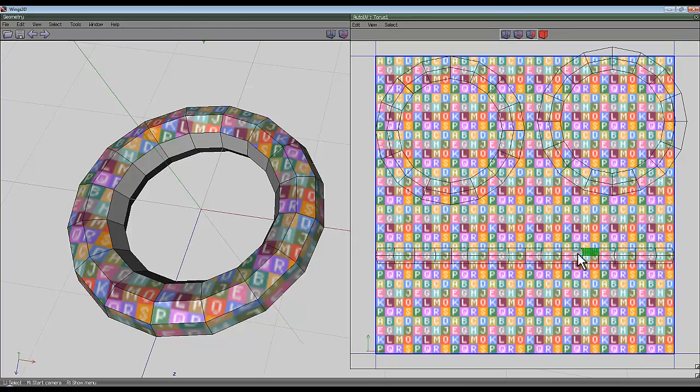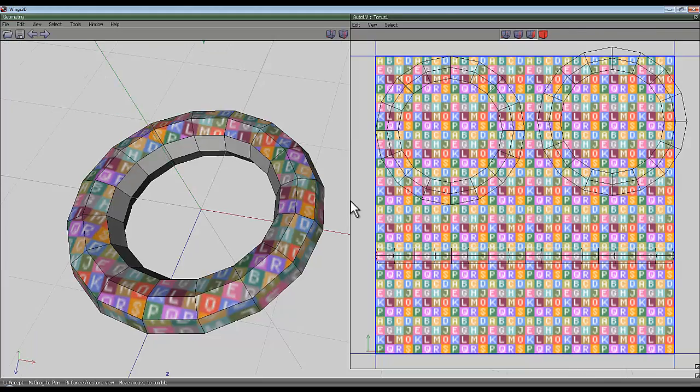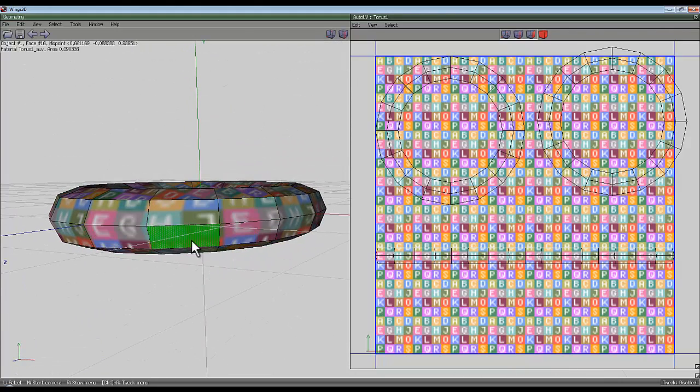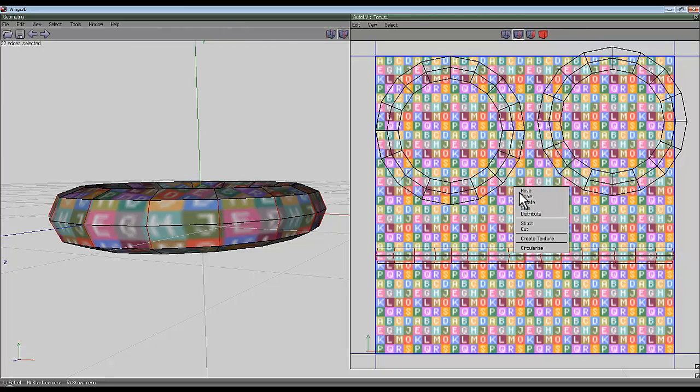Now you can see these lines are a bit wiggly, and that means there's going to be some distortion in the UV map. You want to see these letters being approximately square, and you don't want to see distorted areas. So can we straighten those out? Well, I watched a handy video by, I think it was Age of Armour, and I picked this trick up. So I've selected one in the middle. I know it's not a very complicated shape. One vertical line, and press L for loop, and then G to extend that to the rest of the selection. And then you can right click and you can scale, and we'll do scale horizontally, and you can see how doing that does all these wiggly lines. If you hit the tab key and hit 0, they'll all scale up nice and vertical, which is handy.